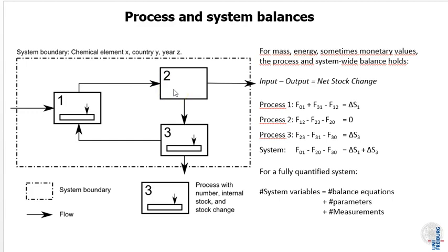And so each mass balance equation constrains the system variables so that the actual number of information that you need is reduced by 1. So the rest of the information can be either quantified by parameters, for example, the two flows always have a fixed ratio, or it actually has to be measured. And again, in the exercises, we will see how that works in practice. Right now, we will continue with a few examples for material and energy flow analysis.